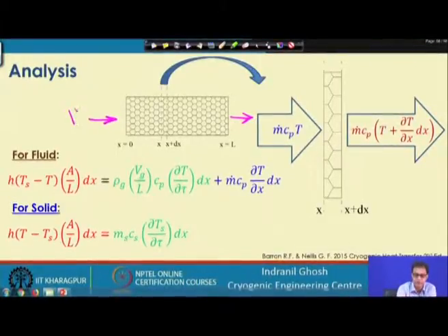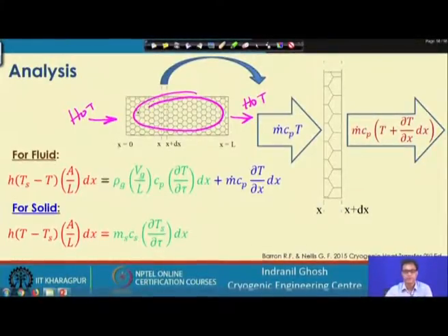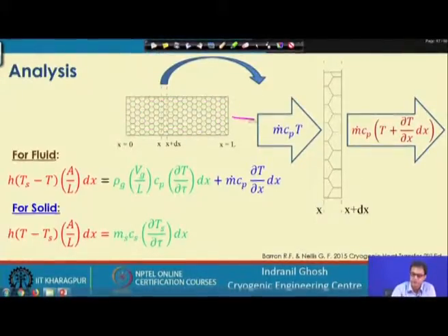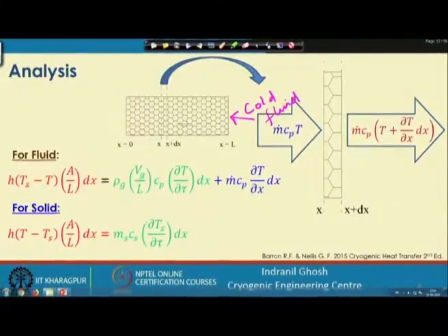The hot fluid will flow in this direction, and this hot fluid will in turn heat up this matrix. In the next cycle the cold fluid flows through in the other direction. This cold fluid will pick up the heat it has left in the earlier cycle. So this regenerator is now hot, and the cold fluid passes through it and picks up that heat while moving out.